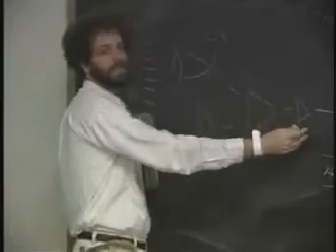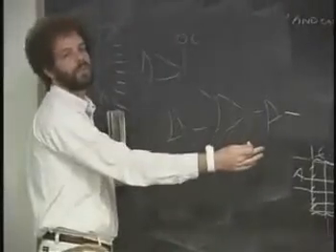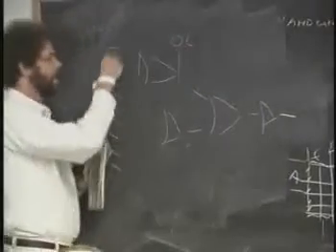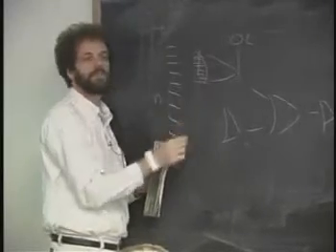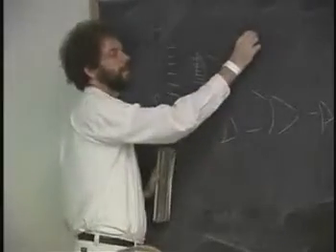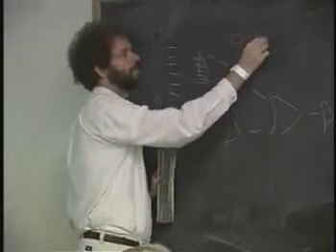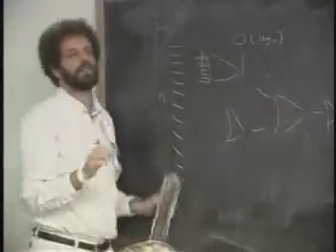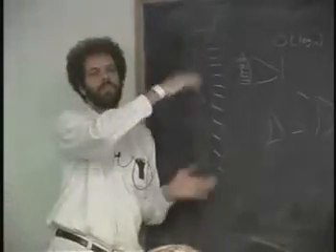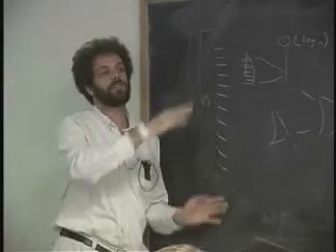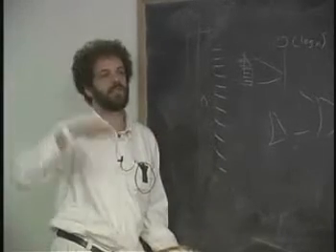So the height of the tree is how long the circuit takes to work, which, if the number of inputs is n and the fan-in is bounded at some number, let's say 10, is order log n. So you cannot theoretically build an adder of a big number of bits n any faster than order log n, as n gets big.